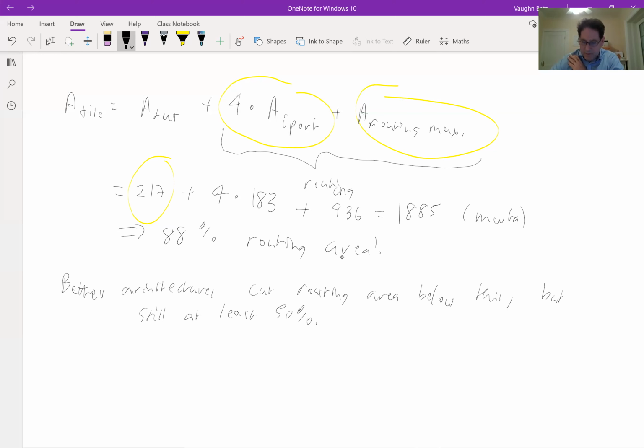I have one question. So these routing architectures, are they all two-dimensional, or do you ever have three-dimensional architectural types, like routing through upper or lower layers? They're mostly 2D. As I was talking about at the start of the class, we'll talk about interposers later in the course. So kind of 2.5D structures do exist. They don't change the fundamental routing structure of the FPGA, at least at this point. They're really made to make bigger systems than you can make with just one die.